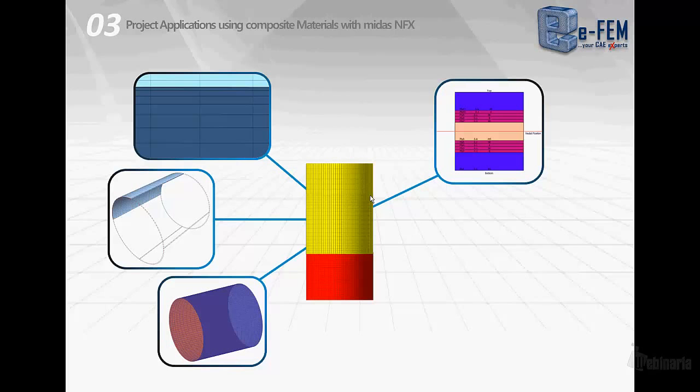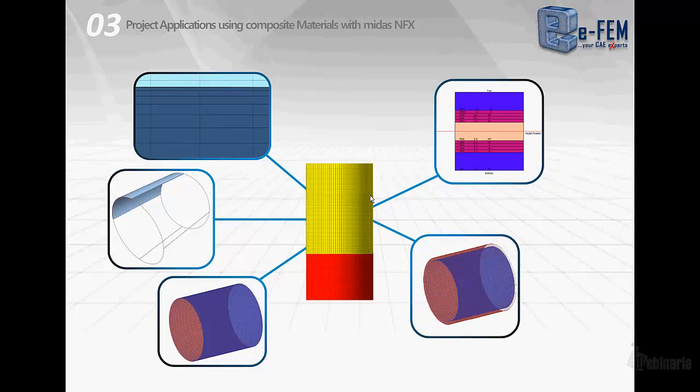The composite has been represented with 2D laminate shell elements, and the stacking sequence has been defined in the element definition. Then the shells have been glued to the adhesive elements, taking into account also the gap that is produced by the fact that we use the mid-plane of the carbon pipe instead of the full thickness of the pipe.